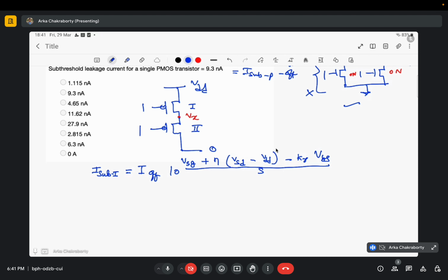All the parameters of the level 1 SPICE model that I have discussed way back, these 5 or 6 parameters would be negative. You can consider either nomenclature. They are basically the same, but it's helpful to solve numericals if you stick to any one of them. Here I have just reversed VGS to VSG for simplicity, but that nomenclature is also fine, and generally the delta one is preferably used in many cases.